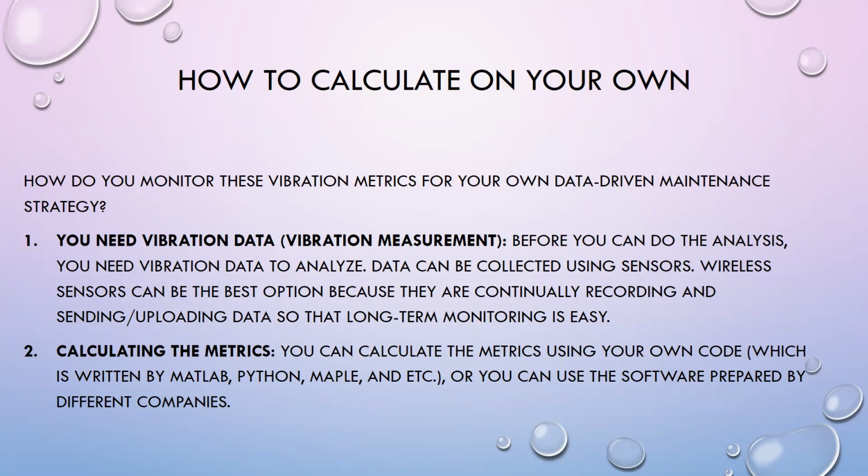You can easily attach them to your structure and then collect the data, and then you can move them to your laptop, to your PC, and then by using different software, you will be capable to do the analysis in time domain or in frequency domain. And the last step is to do the analysis.